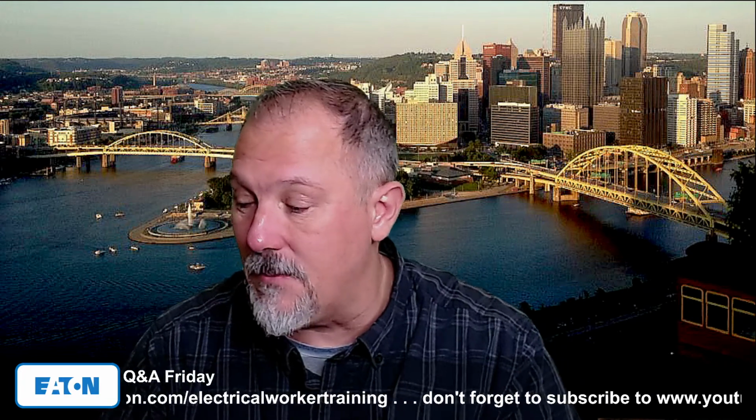So we do test inside of equipment, and that's part of the standards for the assembly as well, like panel boards. We will test the circuit breaker in a panel board, and I know that for a fact because sometimes we'll develop a circuit breaker and you think it's the greatest thing since apple pie. You send it down to your assemblies division. They put it in the assemblies and start putting it through the tests, and they say, sorry, it's too hot. You start to fail the temperature rise. So we do test in and outside of an enclosure.